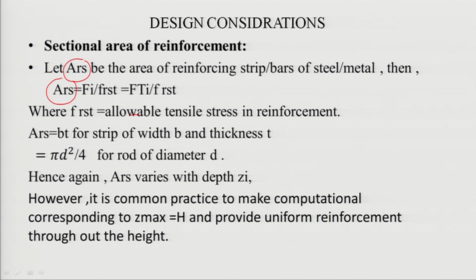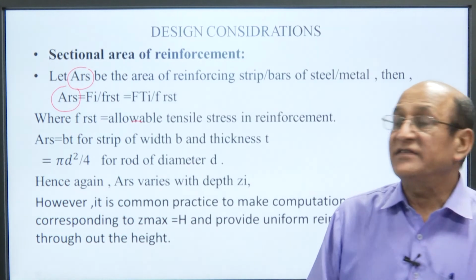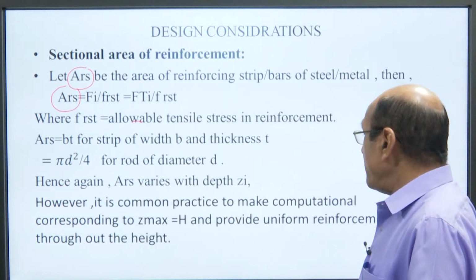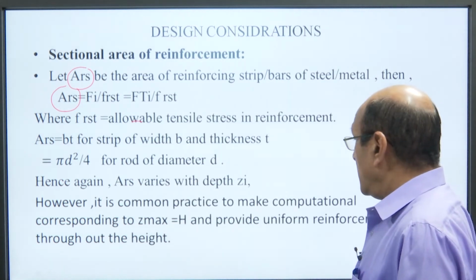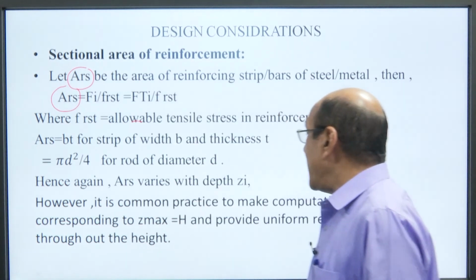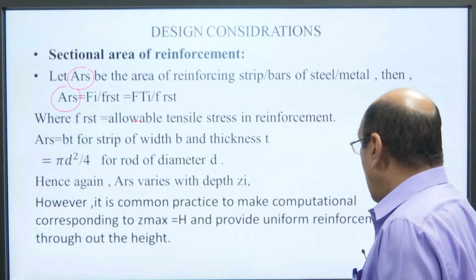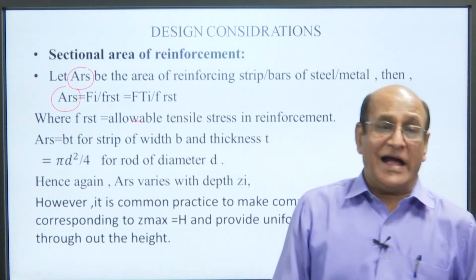Hence, again A RS varies with depth Z i. However, it is common practice to make computations corresponding to Z max equal to H and provide uniform reinforcement throughout the height.